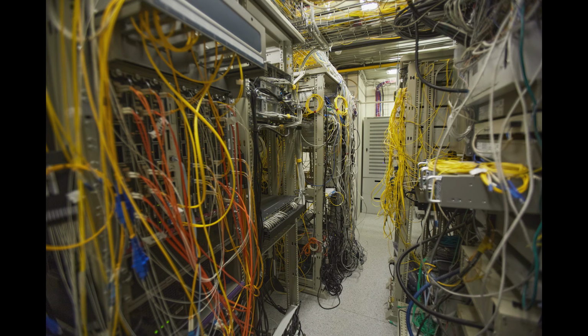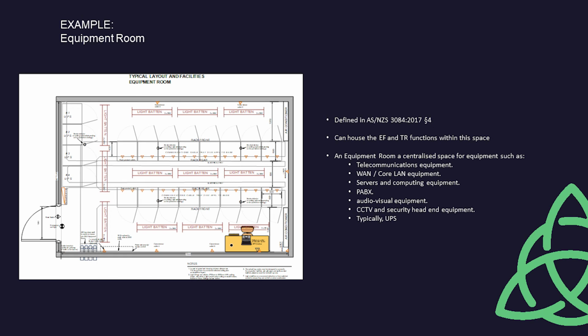By virtue of the intermittent occupancy of the room, automatic switching off of the lights when the room is unoccupied is strongly recommended. The light fittings must also be selected to ensure their installation does not detract from the room's 2-hour fire rating. A maintained emergency exit light or sign must be provided above the door. The door must open outwards to facilitate egress in an emergency.